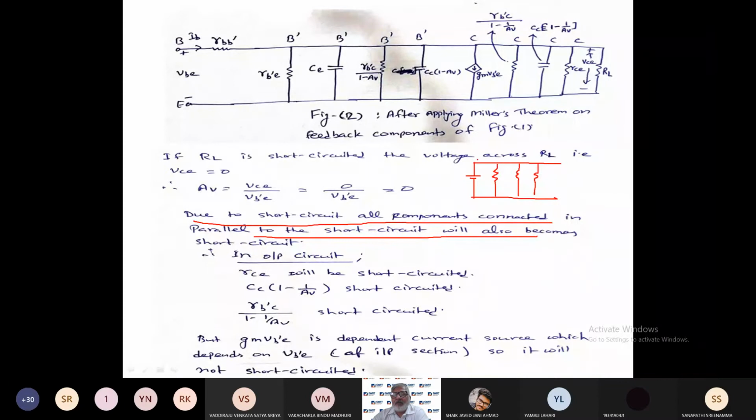So now what will happen? Current will flow in this resistor, this resistor, everywhere it will go. But if you short circuit this, then all the current will pass through this short circuit path. So current will not go in these parallel components, which are resistors. So once you make the short circuit, all the components in the parallel path will be short circuited, right?